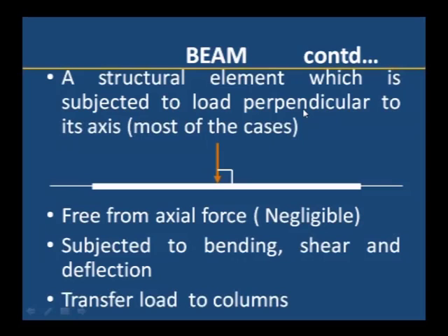A beam is a structural element which is subjected to load perpendicular to its axis. Here we can observe the load acting perpendicular to the axis of the beam. It is free from axial forces; only transverse forces act on the beam. It is also subjected to bending, shear and deflection. In strength of materials, we will study how to calculate the bending moment, shear force as well as deflection. The load is transferred to the side columns.